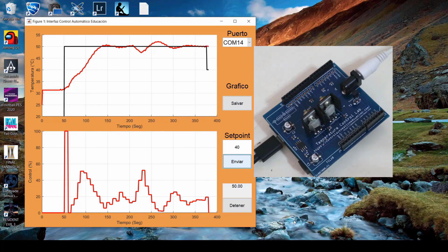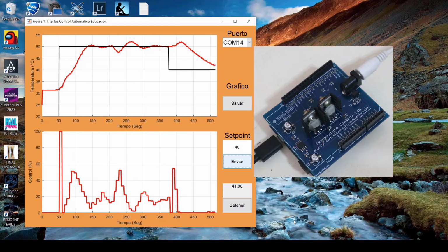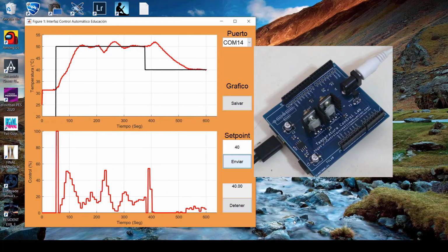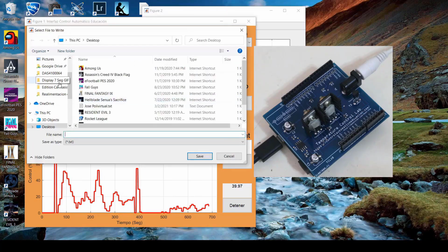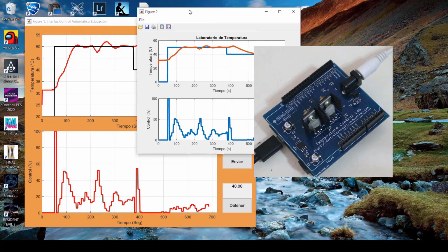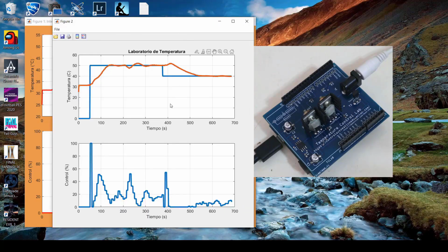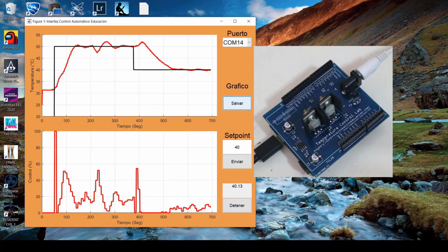We are going to implement a step change in a descending manner in this particular situation because it is descending in a practical sense. Our controller is going to take a slightly longer time. As we have already explained previously, the Cohen-Coon proportional integral derivative PID controller performed flawlessly in this case. We proceed here to save the database of the experiment we just did with this controller on our Arduino so that you can reproduce it, and your task is to analyze what the dynamics of a PI will be and compare it with this response that we have obtained from the PID control, which is quite good,